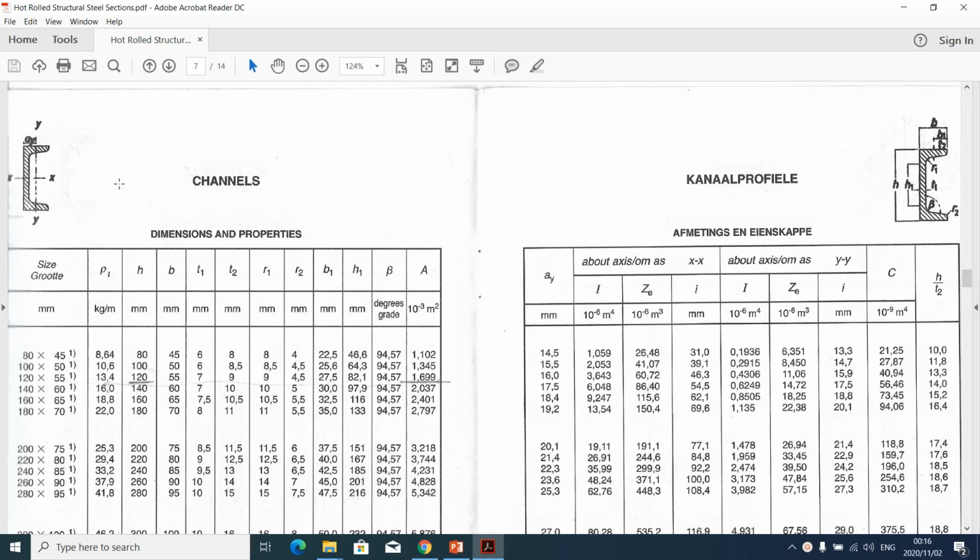So that is a very important thing, that you're not going to go under XX to locate your inertia. You'll have to go to your YY axis to locate your inertia, which is 1.135, because your channel is no longer upright.